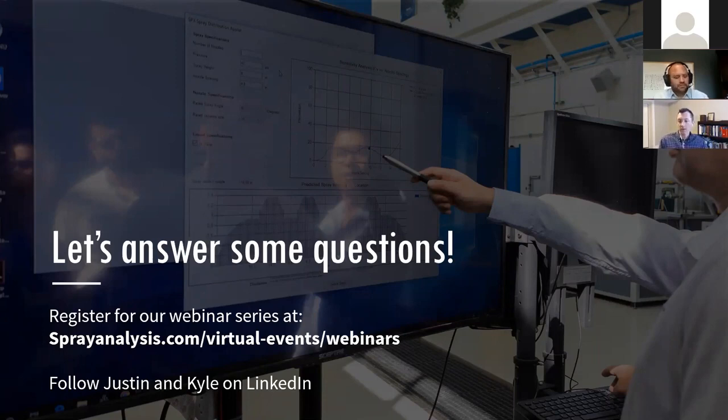Yeah, so we refer to this as heavy edges, and a lot of times either high viscosity or high surface tension sprays can have this. And so increasing the temperature to reduce those properties could be beneficial. We could go to more of an air atomizing nozzle, or sometimes it can be difficult ahead of time to decide what nozzle or what nozzle technology is going to make a spray improve. And at that point, it's typically easiest to bring some of the material into our lab and try spraying it with a few different options rather than sending nozzles back and forth.